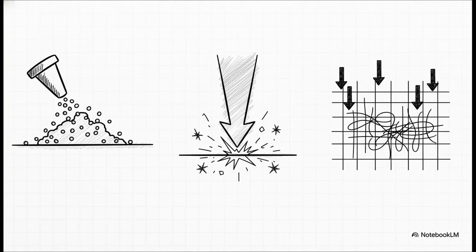Next up, as we start building up those layers using chemical vapor deposition, PVD, or ALD, new risks jump into the mix. Poor nucleation introduces structural irregularities in grain boundaries. That leads directly to uneven electrical conductivity and dielectric breakdown. On top of that, energetic plasma etching literally breaks surface bonds, bringing in plasma-induced contamination.